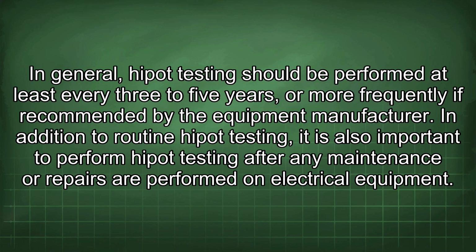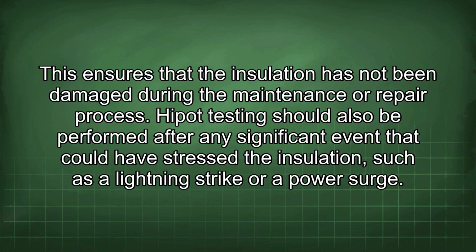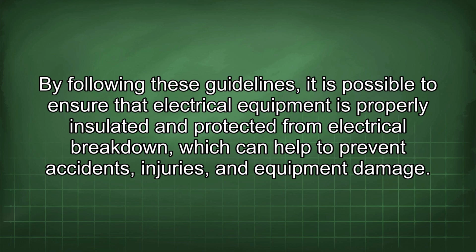In addition to routine Hipot testing, it is also important to perform Hipot testing after any maintenance or repairs are performed on electrical equipment. This ensures that the insulation has not been damaged during the maintenance or repair process. Hipot testing should also be performed after any significant event that could have stressed the insulation, such as a lightning strike or a power surge. By following these guidelines, it is possible to ensure that electrical equipment is properly insulated and protected from electrical breakdown, which can help to prevent accidents, injuries, and equipment damage.